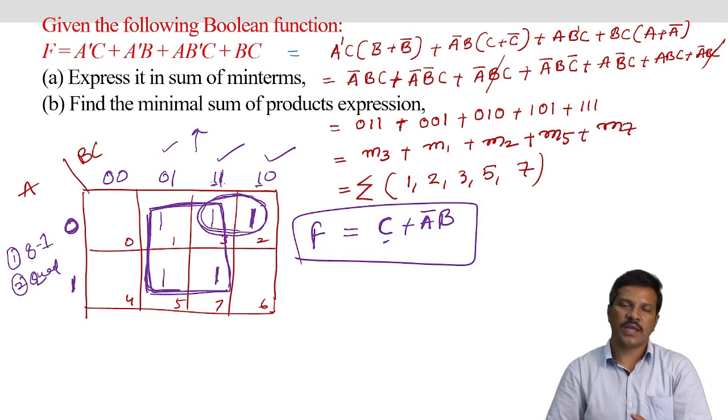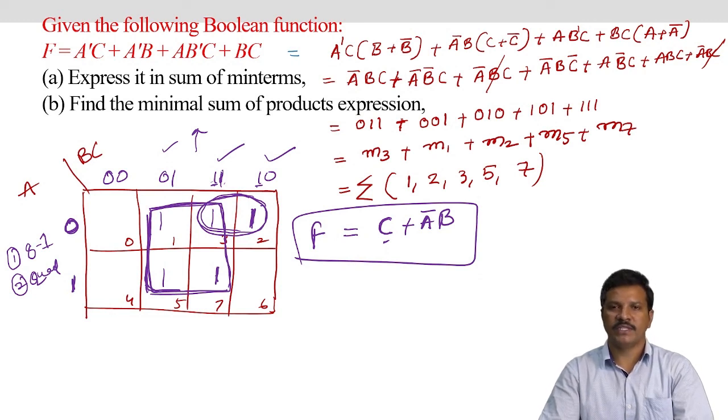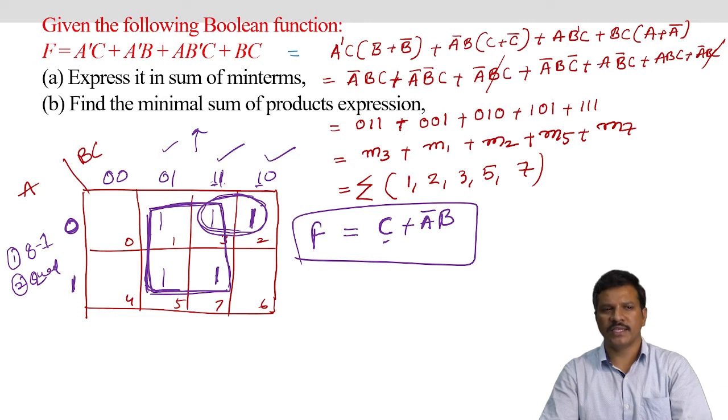Likewise, we can perform the Karnaugh map method to minimize the Boolean function. The important thing is remembering the order of the square box values, then placing the minterms, where the corresponding square box value is 1 whenever that minterm exists in the Boolean function.